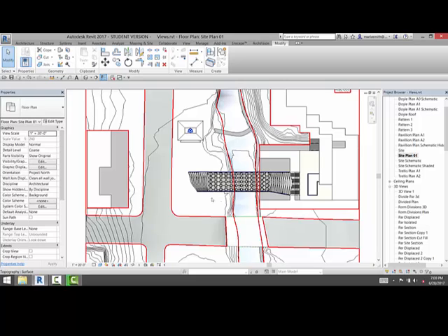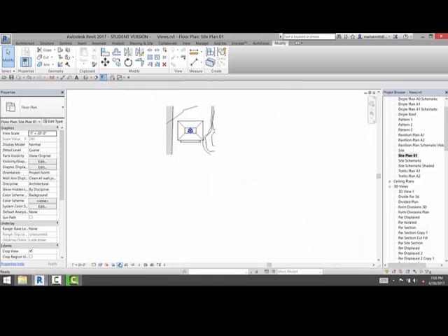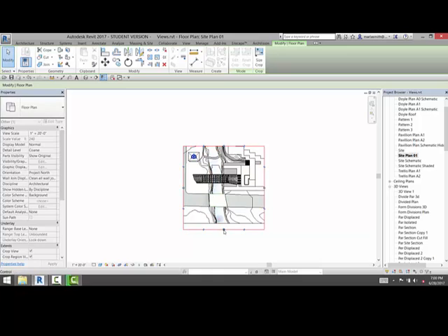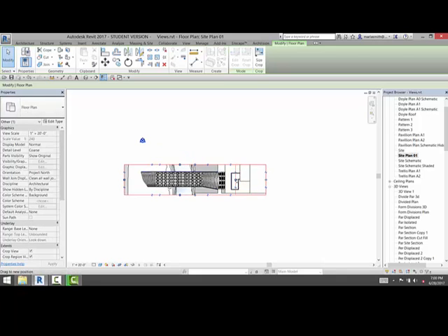Now I want to crop the view. So we know to do that, we can come down here to crop view, and it will crop it, which it's cropping it to a tiny, tiny little piece. If we turn on our crop region, show the crop region, if we pick that, we can pull it out and adjust it to what we want it to be. We could also set it to a scope box, which we've done several times as well. So you could come in and pick kind of about where you want that guy, right?